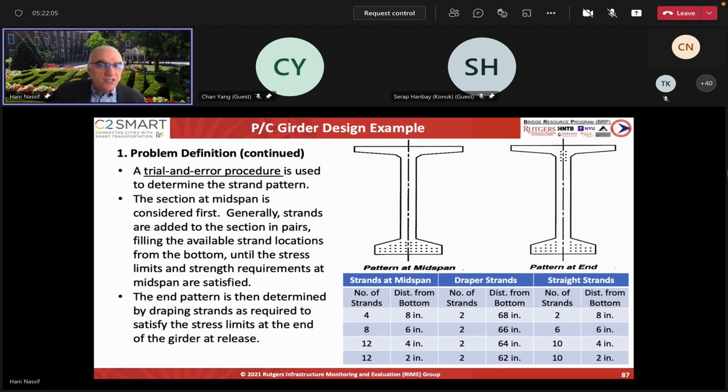So what you need to do is make sure the eccentricity of the tendons at the support becomes close to zero. I mean, you might not be able to harp all your tendons up, but at the end, some of those tendons that are here, we move them at maybe 0.4 L or 0.45 L, and you start going up with those gradually. And then you end up getting them all the way to the top of the girder.